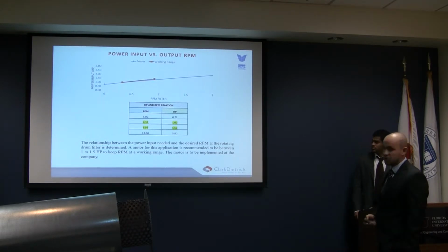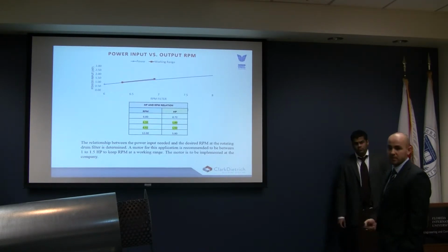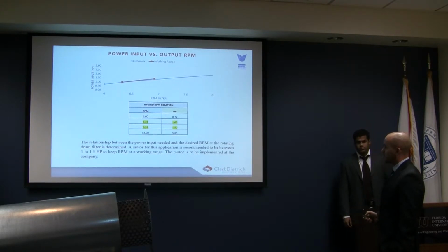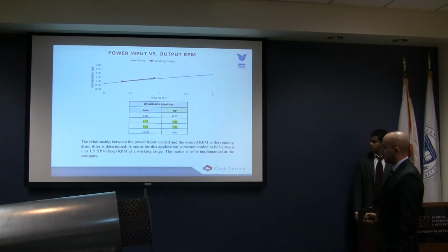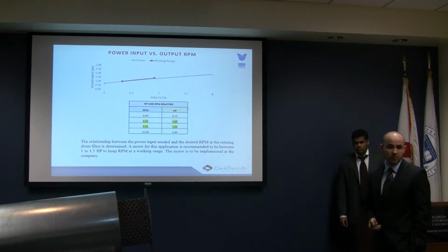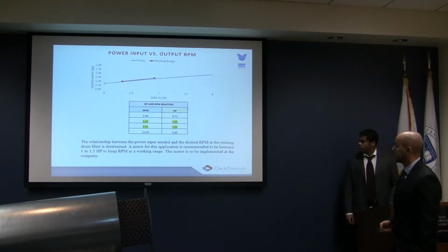If we go to each catalog, we can find that the motors come in certain increments. So our best bet was between 1 and 1.5 horsepower for the motor at the driver.